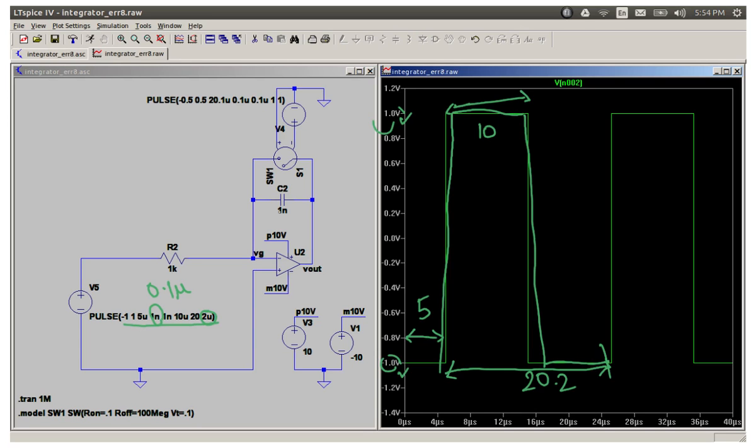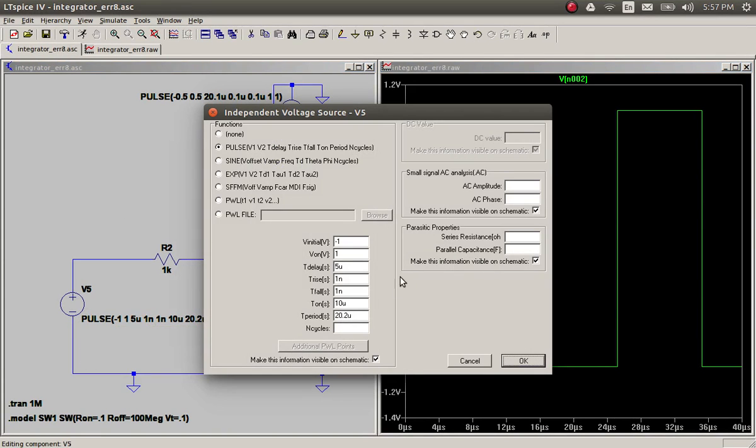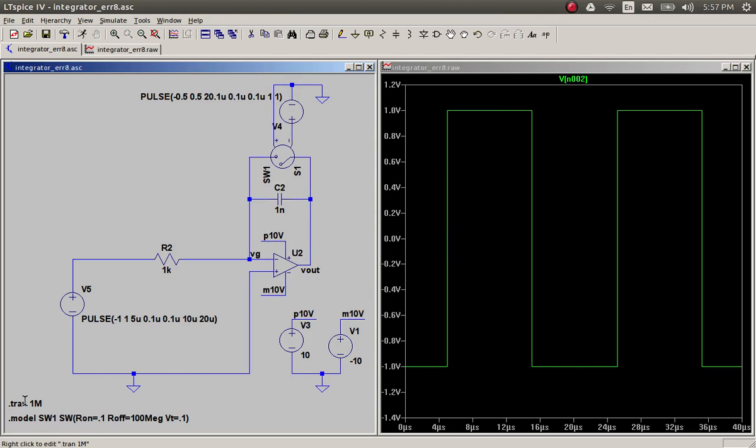So let's look at that. So let's change it. We made the rise and fall time very very small. A nano is 10 power minus 9, so much smaller, 10,000 times smaller than a micro. Okay, I'm going to remove the caps, it's bothering me now. No, yeah, there we go. And I said, my on time is 10 microseconds, so my period should just be 20 microseconds, and that should give me 50-50. So if I did that, and okay, let it simulate.